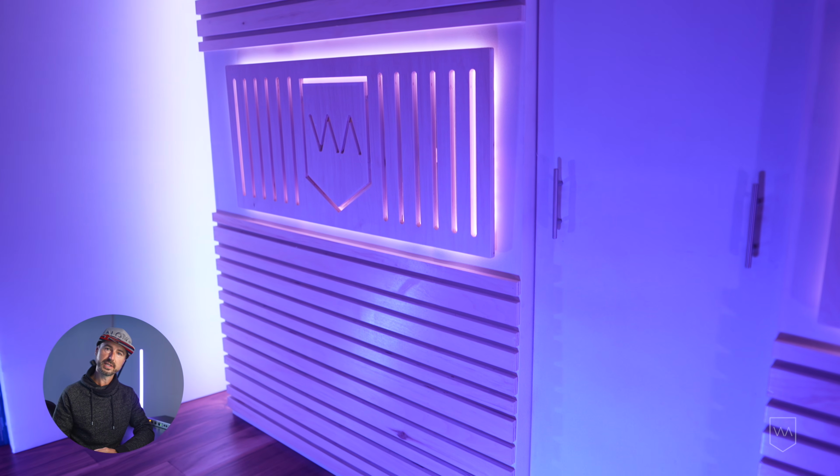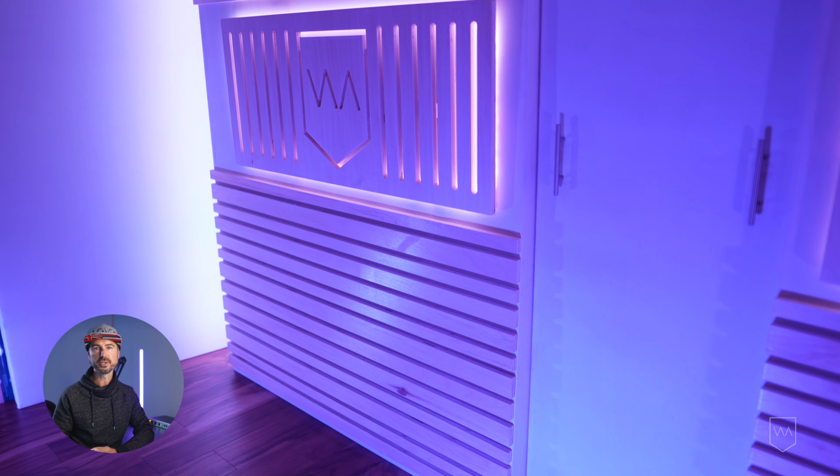In a small room, it is entirely inappropriate to use diffusion. The walls, the boundaries are simply too close to you. And if a diffuser is within 10 feet of your listening position, you are really, really going to hear it. And it's going to actually cause a detrimental effect to accuracy in the room, causing reflections within that Haas fusion zone that are going to blur things. Also, another big mistaken thing in studio design is people think that diffusers are going to do something about the low end. They do not.